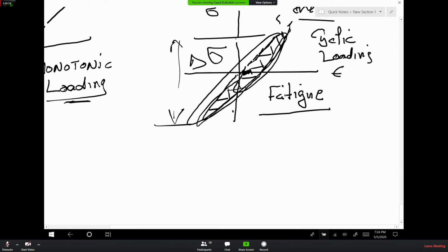And because they unloaded the shipment not evenly, that's delta sigma. So between delta sigma and delta T and the corrosion, the crack kept growing and nobody was watching it till it reached a critical size and the ship broke. And that's one of the first cases of what they call fracture mechanics.